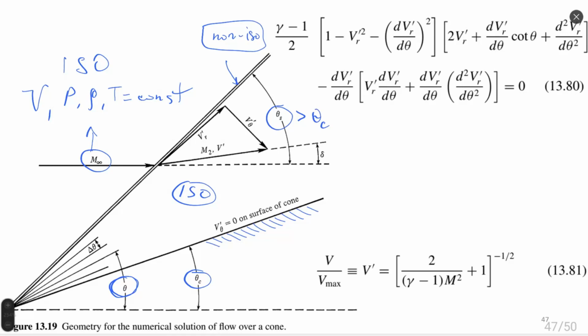In all other regions, flow is isentropic, and we can use isentropic functions to obtain flow properties, thermodynamic mostly, as functions of Mach number. So we calculate velocity behavior, we calculate Mach number with equation 81 corresponding to the velocities we obtain, and we calculate all other thermodynamic properties: density, pressure, and temperature.